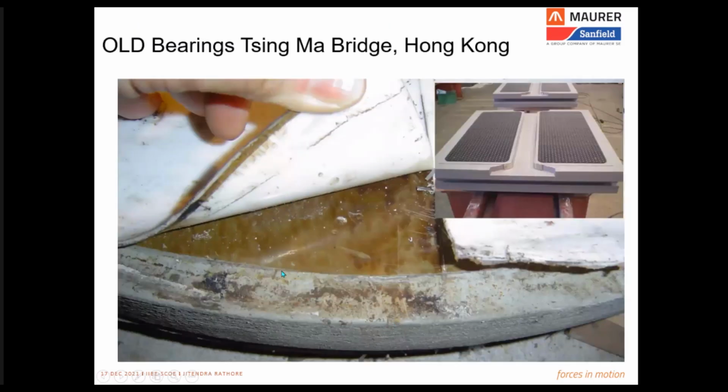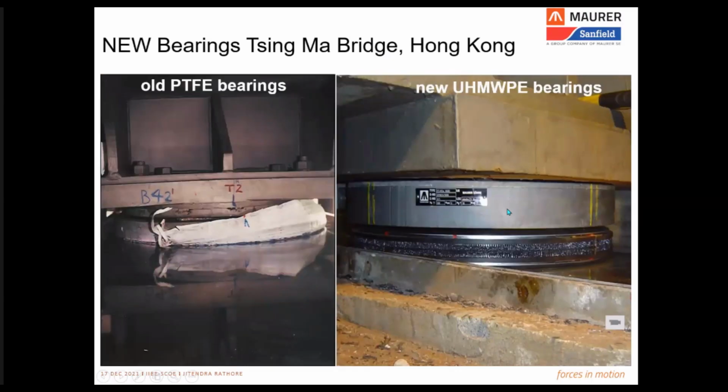And then the design of these bearings was improved and the sliding material was changed from PTFE to UHMWPE. And the first batch of replacement of bearings in this bridge took place around the year 2000. And since then, it's already more than 20 years, and the replaced bearings are performing satisfactorily.